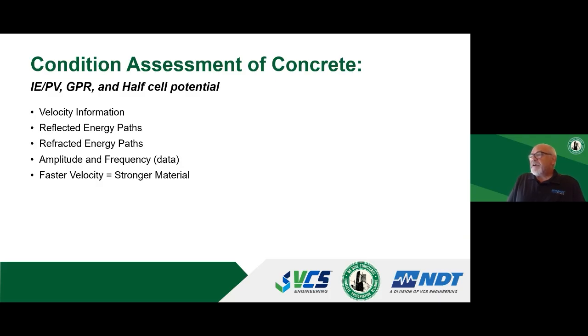But for condition assessments of concrete, we want to understand how energy waves move through solid concrete or through soil or through rock. And we're recording the velocity information of how these sound waves go through, and if they get reflected and refracted off of anomalies, or maybe don't even go through a crack. And we're also measuring the frequency data, which is based on the amplitude of these energy waves. These are compressional waves and shear waves. But a rule of thumb is if the energy wave is faster, if the velocity is higher, it's likely going through a stronger material.